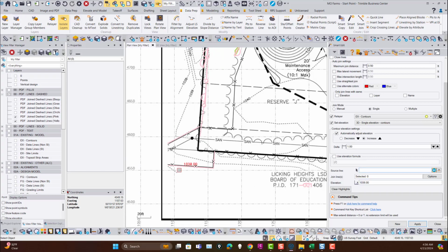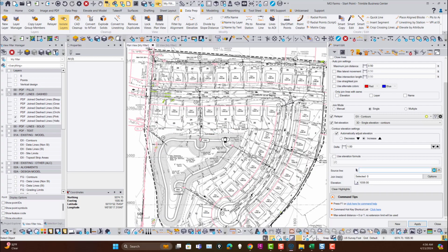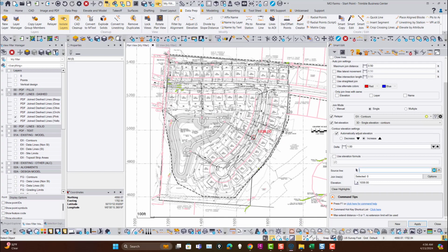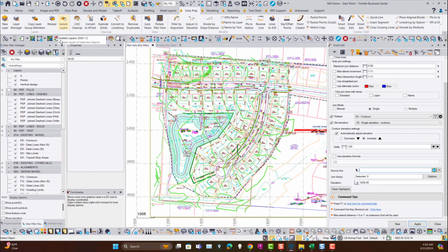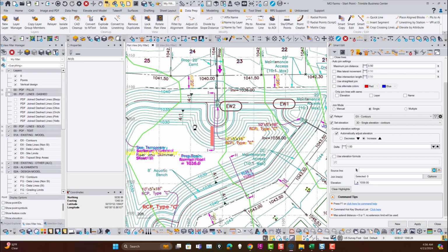And enter. So now we've done all of those contours there. Everything on that is elevated, and you're ready to go to the next level, which is to do the design contours. So then we would unisolate and do the same thing again. In this case I just unisolate the layers, which is on Control 1 or the button up here, and then I can say turn off the dashed lines. Let's turn on the solid lines now, and there's the solid lines.